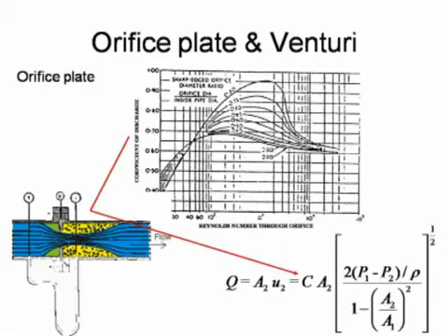So the last thing to consider is this discharge coefficient, which its name gives it away really. It's a coefficient, it's not a constant, and that coefficient depends on the Reynolds number through the orifice and also the design. So we can have a chart, and you can see here that for Reynolds numbers really above 100 and through 1,000 to 10,000, we're typically looking at a discharge coefficient of 0.6 to 0.7-ish for this particular orifice plate. It will change a little bit with the design of the orifice plate, maybe even getting as high as 0.9, but a typical value is 0.6 to 0.7.